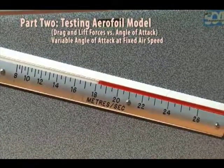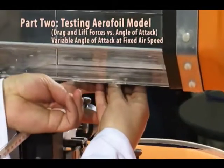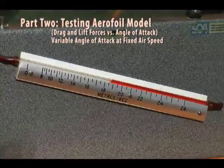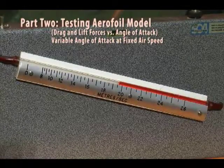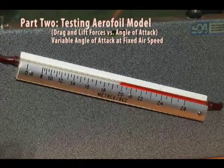When measuring the drag and lift forces, it is important to reduce the slot in the tunnel base as much as possible, using the cover plates provided. In this part of the experiment, the Reynolds number should be fixed by fixing airspeed within the range of 18 to 25 meters per second.